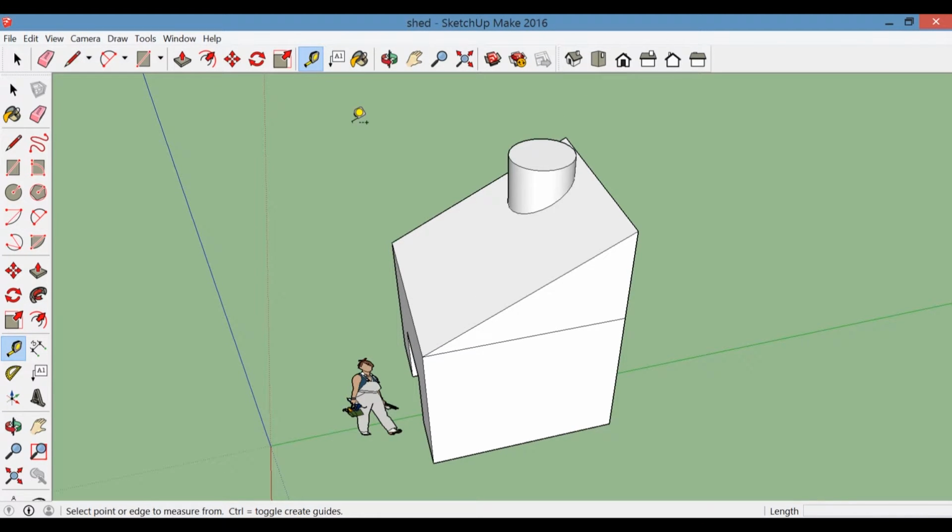So just now when I was demonstrating the tape measure tool, you might have noticed that when I placed it near this circular chimney thing, the center of the circle appeared as a dot, so I could find where it is. This is an example of an object snap, and what these do is that they judge, based on the context of your action, what you might do next, and in turn they will modify your action to help you draw what you want to draw accurately.